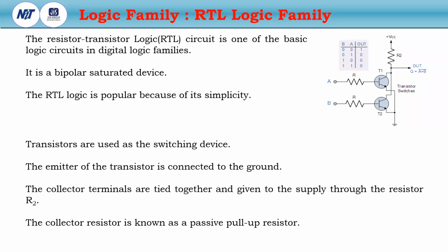This is also called the passive pull-up, because when these two transistors are in the cutoff state, then the output will be logic high. So the resistor acts as a pull-up resistor. This is R and these are the transistors. For this reason, it is called RTL, resistor transistor logic.